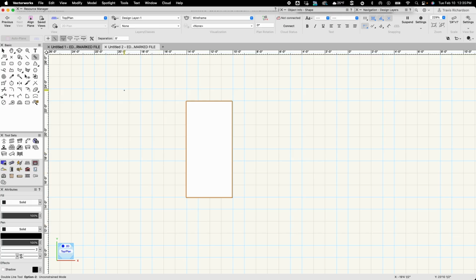Let's say I want to do the framing for that now, and I'm going to frame that out in 1x material. So the edge is going to be 3/4 of an inch. So now I can say, great, I want to frame that out like so. And there's my framing without the toggles. I can obviously enter those in as well, but that can be a really fast way of putting information in.